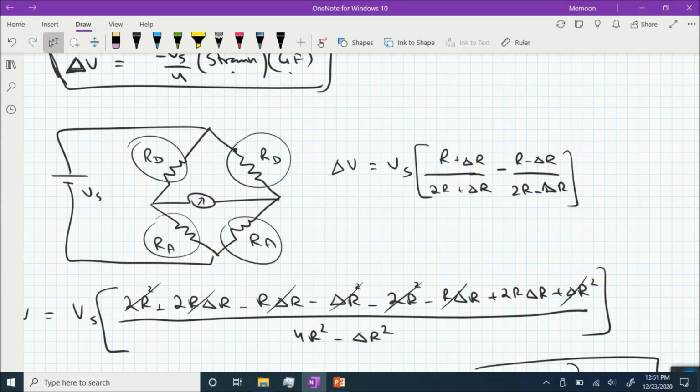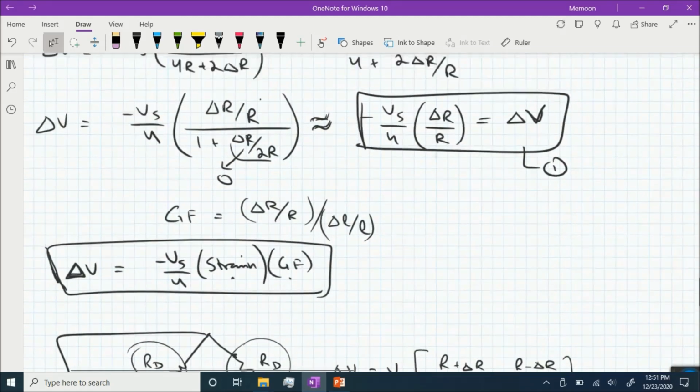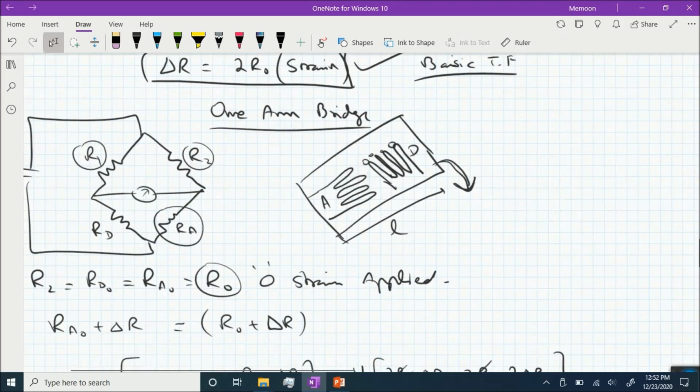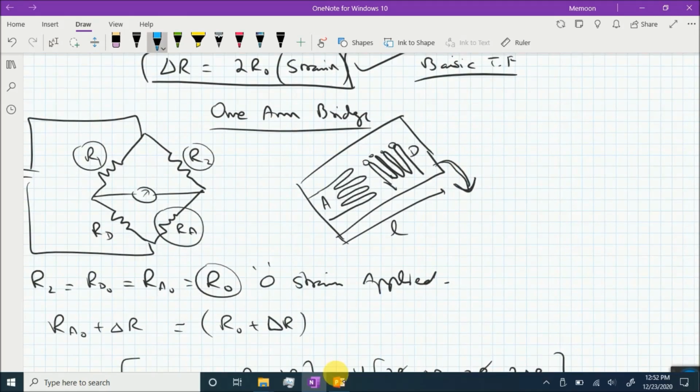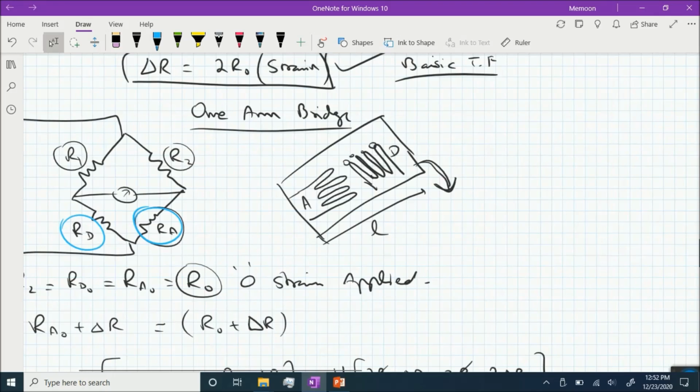And lastly, coming to how these dummy cells are compensating for the temperatures for which they are being used, let's see here. If the bridge was at null, and the temperature rises, the resistance of both RA and RD will rise, and they will rise with the same magnitude.